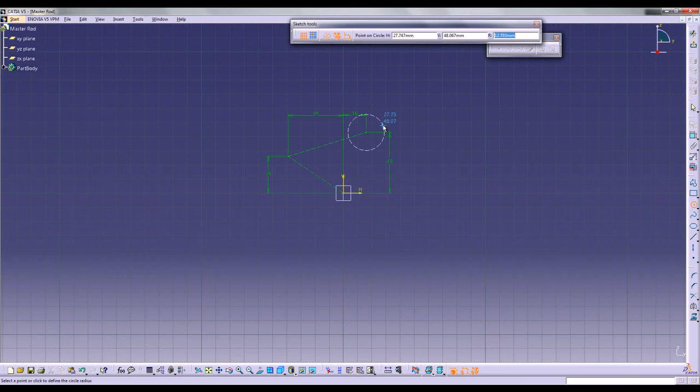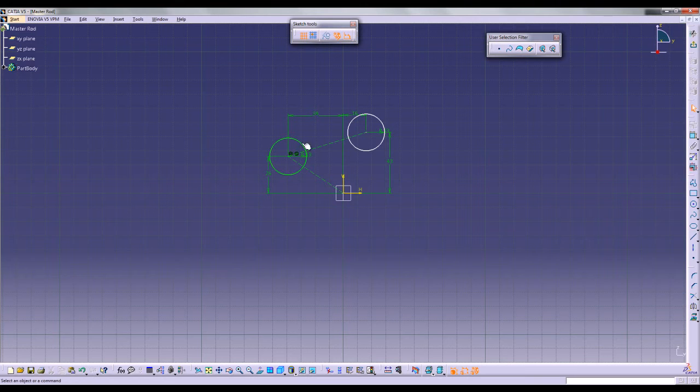Now I'm going to start making the outer shape of the flange using circles that are going to be concentric with those points I just found. I want them to be standard elements, so I'll shut off the construction elements icon. And they have 13mm radius.